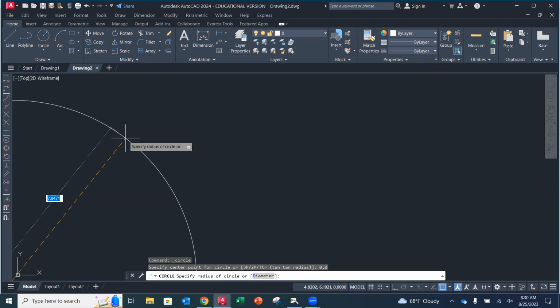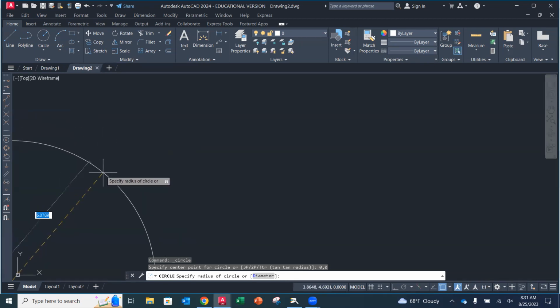If you have it set at the world 0, 0 in AutoCAD, when you pull that into another program that is going to read it for a tool path, it's going to correlate that 0, 0. It's a nice thing because it's fewer steps when you set it up and pull it in. So whenever you can put it at 0, 0, even if you're thinking, I'm never going to use it like that, that's fine. Then just click wherever you want. But starting with the origin is a good idea.